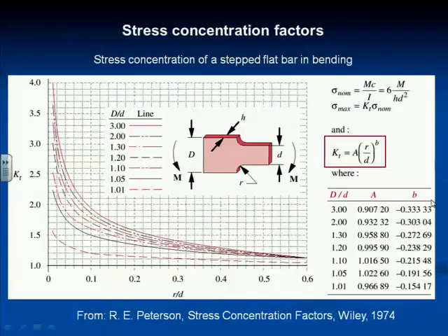And all materials have cracks from the factory. They may be so small you can't see them, but they're there. And microscopic cracks are sufficient to start the process, which is called crack growth. And when it gets big enough, the thing fails. And there are ways, as we will discover in the next few weeks, that we can design to avoid those for a long enough time, like billions of cycles, so this thing is probably in the dump anyway.